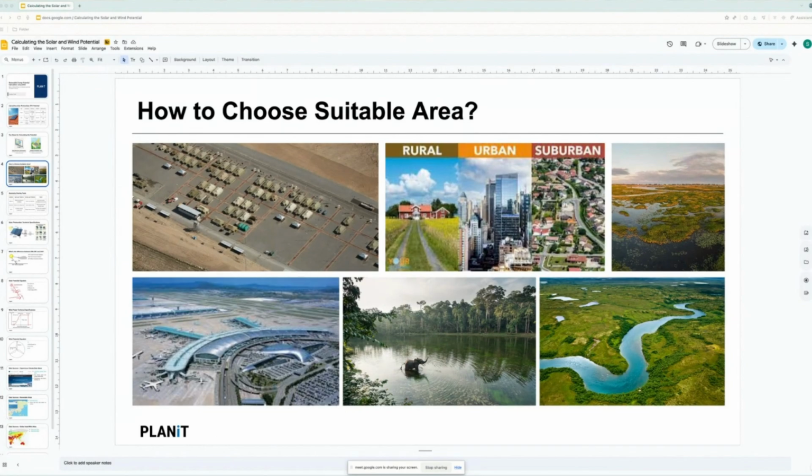And then yes, mountain. That's a very good point. I mean, not all mountains should be avoided. It depends on where to put more value, but you can build solar PV in mountains. However, building solar PV on mountains costs a lot because it's not flat, and access to the mountains with all that equipment is not going to be really cheap, right? So mountains are usually avoided.